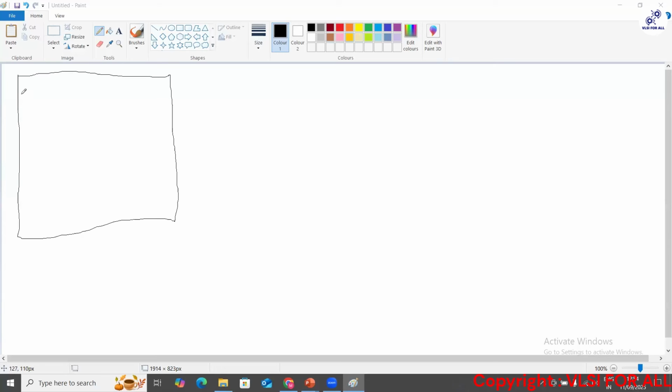See, let's say for example, when initially you had no notion where your flops are going to be placed, right? Because right now you're at the synthesis stage, not at, let's say, the PNR stage. For example, I'm giving you a very high-level view of what happens. These inner boxes, let's say, are all flops. Now the scan team gave you the connectivity in the form of a DEF.